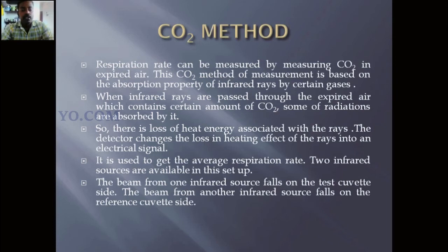During the radiation, the infrared rays are absorbed by the carbon dioxide. So there is a loss of heat energy associated with the rays. The detector changes the loss in heating effect of rays into an electrical signal.